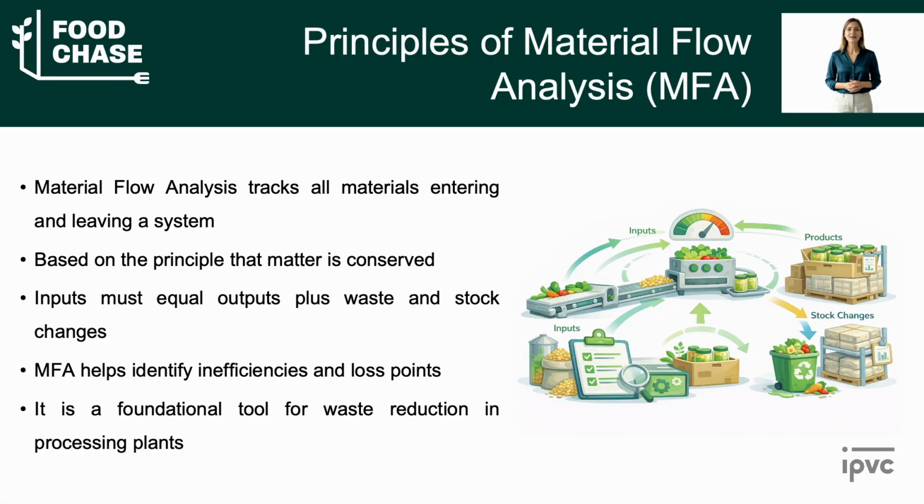Material flow analysis, or MFA, is a key tool used to understand and reduce waste in food processing. It is based on the principle that matter is conserved, meaning that all inputs must appear as products, byproducts, waste, or stock changes. By systematically tracking these flows, MFA makes inefficiencies and hidden losses visible, providing a solid basis for targeted waste reduction measures.